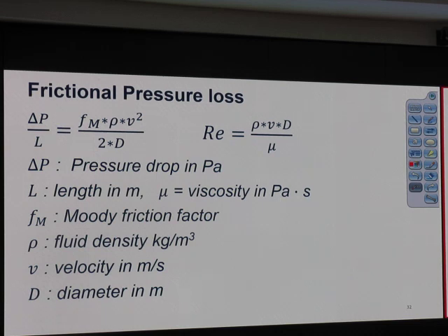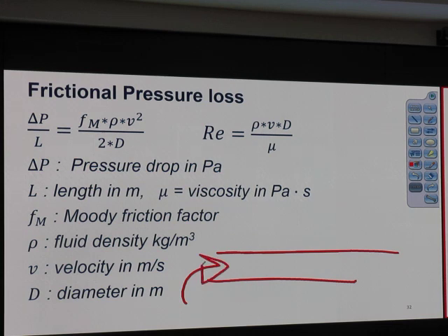For a subsea pipeline, it is insulated, if not buried. It's always insulated, but there is a heat loss to the environment in a subsea pipeline. So this means at the wellhead, it may come hot at 130 Fahrenheit, but subsea condition is 40 Fahrenheit. It flows for a while, it gets colder and colder. So when the temperature drops, what happens to the viscosity?